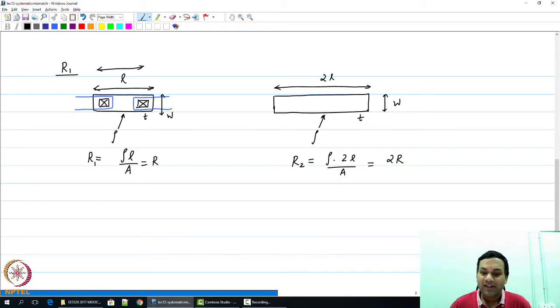Now unfortunately, it turns out that there are some other aspects to take care of. So first of all, the resistors that you connect to the rest of the circuit, you need the metal wire and the contact. So let us assume that the metal wire is ideal for this purpose. In reality, that may also affect your design. Let us say it is the contact that has some resistance small r.